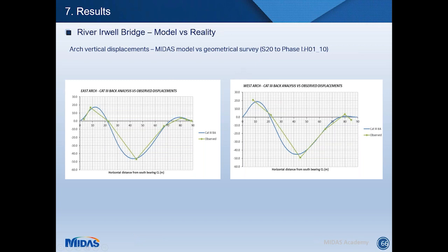This in particular is the first phase of stressing and the installation of the first 10 hangers, really. So the displacement is really well captured by the model, as you can see, and all of the points that were read on site basically lie on the displaced curve obtained from MIDAS.